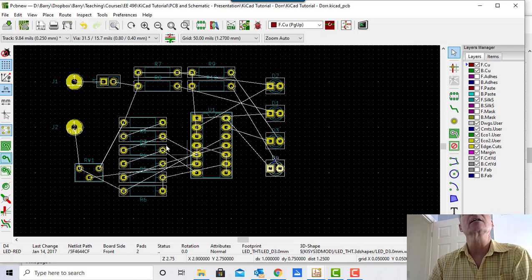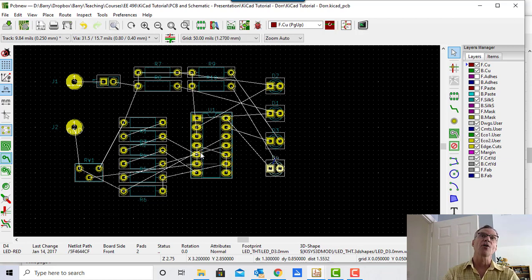Do I see a lot of lines crossing around our LM339? Yeah, I see some. Let's say there are too many crossing lines, and I say, if I just reassigned the pins of that LM339, I could get a lot of these lines to not cross, and I'd have a cleaner layout.